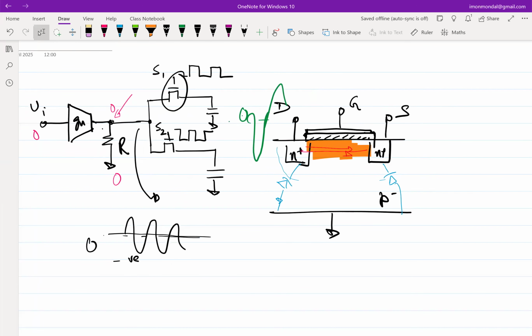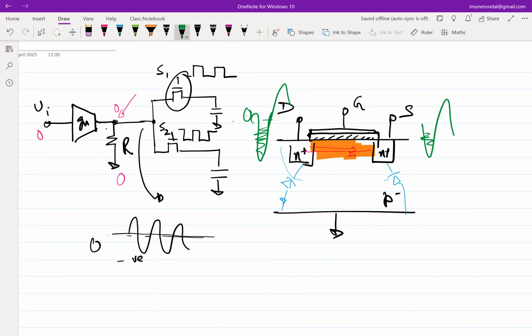So when the drain or the source goes negative, then you have real problems. So this guy will have problems, right? In your simulation, you might not see hard clipping because these are not like those ideal PN junctions that we study in basic electronics, that beyond 0.7 or beyond 0.3 or whatever, it starts saturating. So you are going to see a considerable amount of current flowing into the body. And there will obviously be distortions because of that.